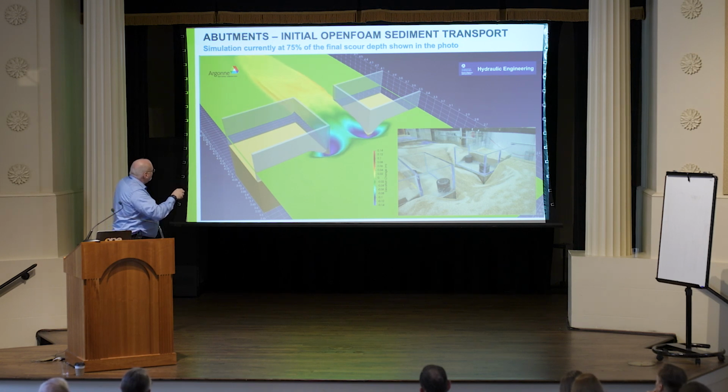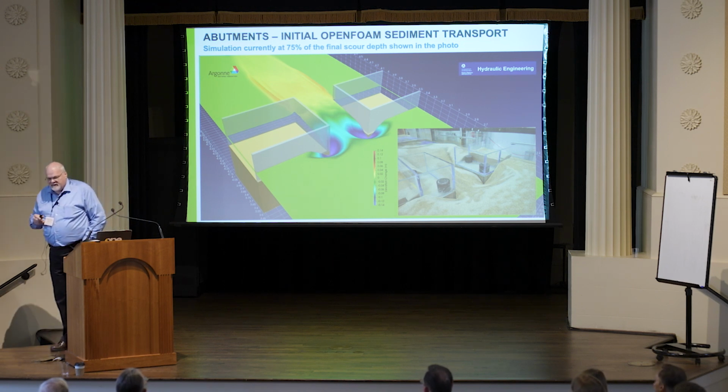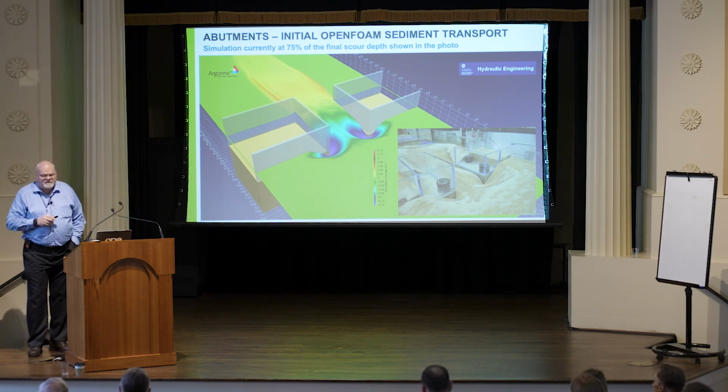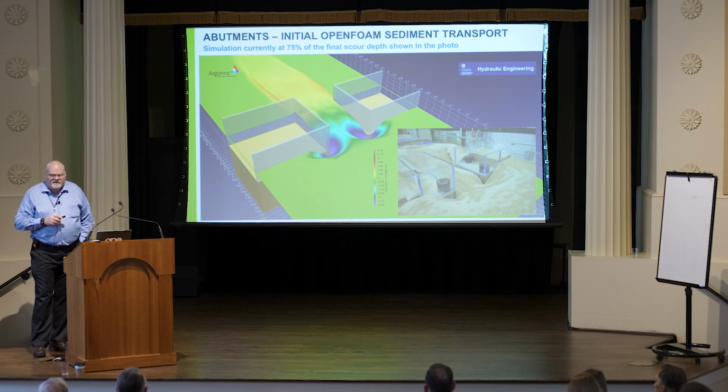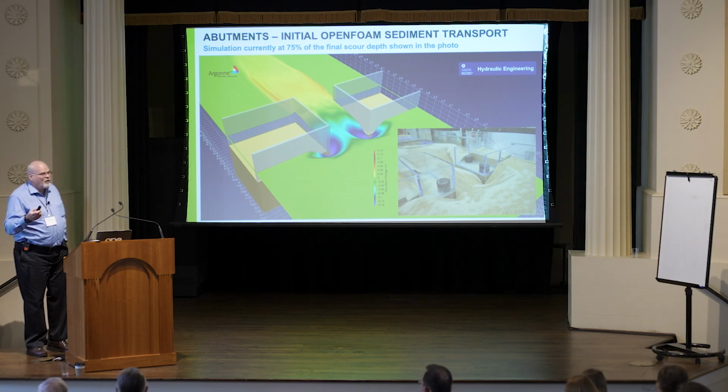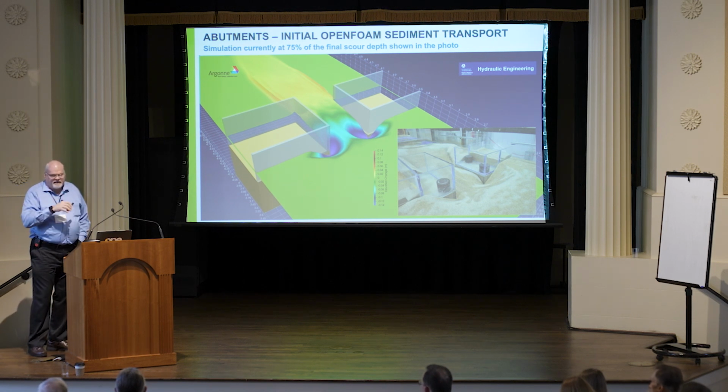What we would expect now is that the material behind the piers spreads out a little more. Now here's another simplification that we had to make to save compute time. This is a K epsilon model, right? So turbulence is modeled in form of more energy, basically thicker water when you think about it, right? And so with this kind of model, you don't catch all the eddies that shed off at the corners after the opening and things like that, right?